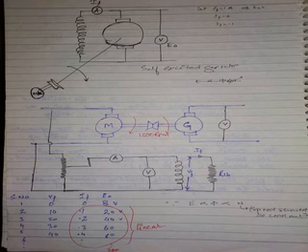If you know this 100 ohms, you can easily plot that line. 100 ohms is nothing but VF by IF. You can take VF as 100, IF as 1 ampere. You know 50 by 1 is equal to 100 by 2 is equal to 200 by 4, like that. It's a linear curve. If you know one point, 100 and 1, automatically you can plot a line from the origin. So you can mark 100 volts here, and automatically 1 ampere, you can make a point, and this point is joined from the origin.